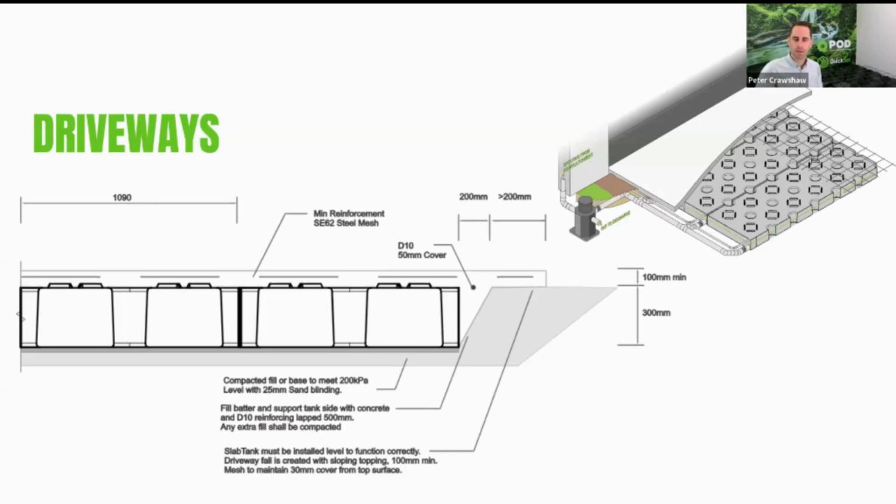Those load points are bearing down on your improved ground. And those load points are at 550 centres, and it's a 160 millimetre diameter lead going down, which is tested to a 6-ton jack point loading without failure, between the two load points. So you can see it's perfectly suitable for driveways, for garages in that respect.